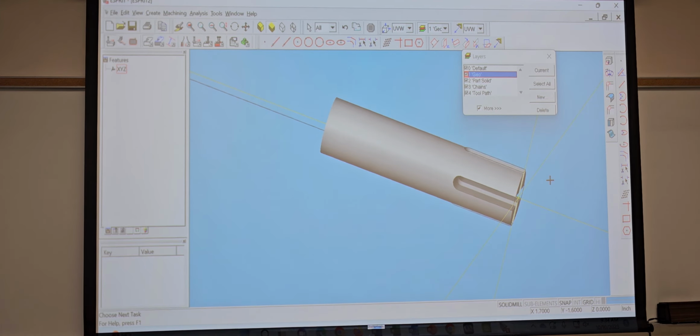We can go through it real quick. I think we need the squares in order to machine the slots, right? The way I did it this morning, I just went through and did the slots, and that actually ended up working today without having to change the axis orientation. As long as you do it in order, it's better, because if you don't do it in order and you switch, and you forget to switch back, and if you pick an operation, it's going to remember that one, and that's when you have to go to system default on everything.